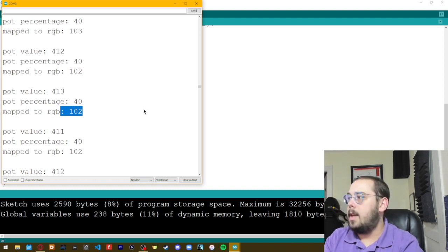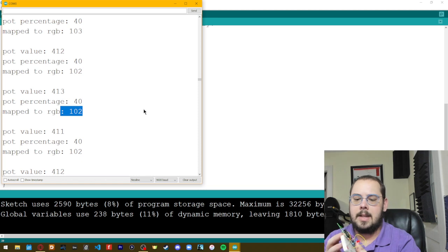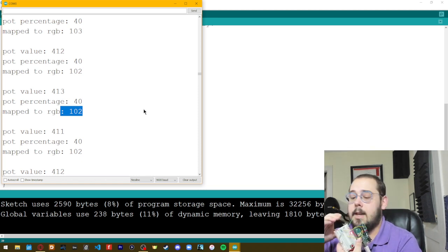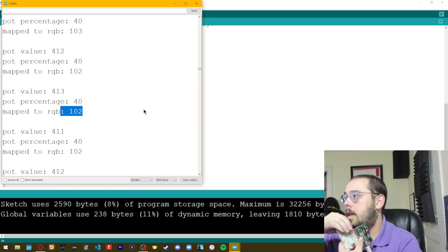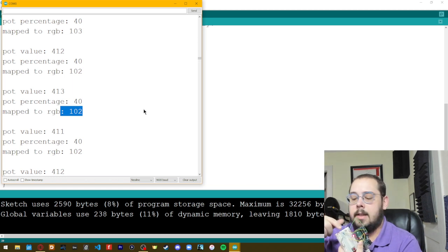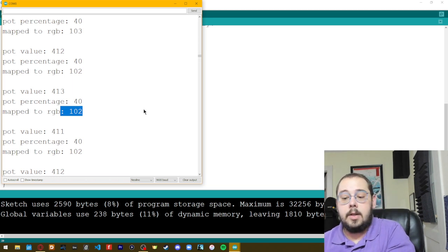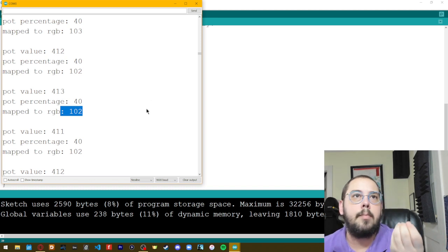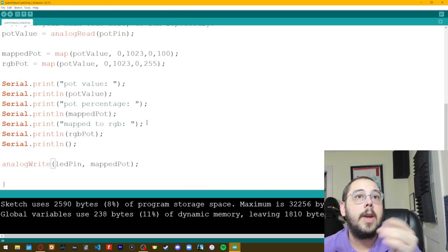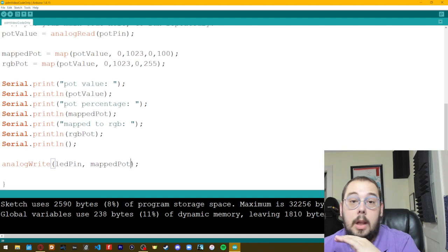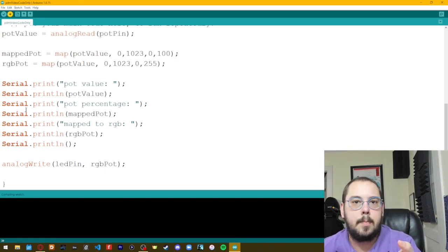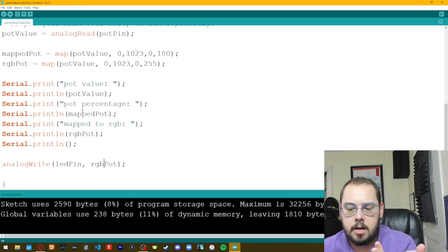Just generally looking, we can see, because I've still got the wrong sensor hooked up, it's not super accurate, but as I cover this, that LED dims, and actually I can get it really dim, and then it'll brighten up when it's exposed to light. So we can use that to control the perceived brightness. Again, what is happening is we are turning it on and off a lot, way faster than we can see. We are just perceiving it as being 75% on.